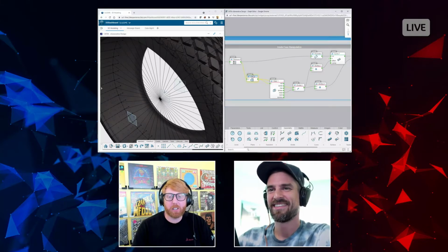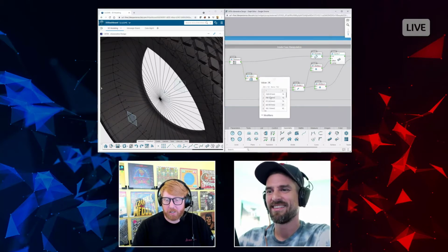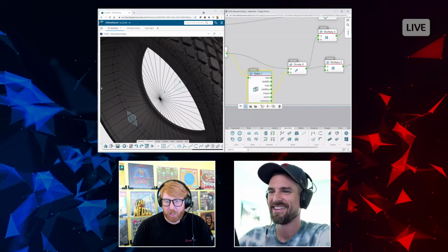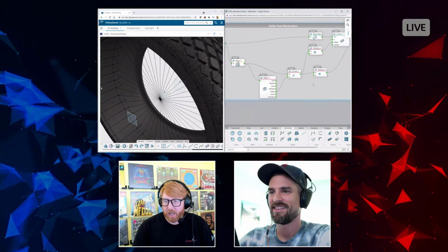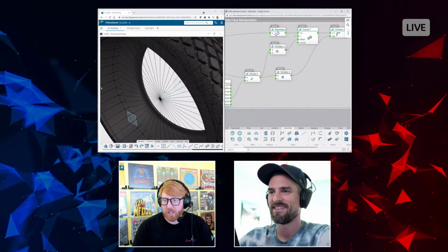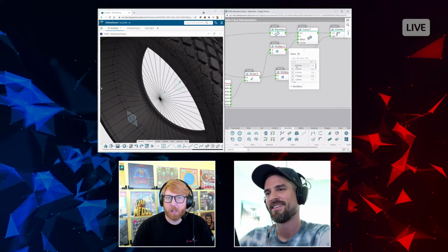So now what I do is take the surface area of all 792 nodes and run it through some logic where I get the stats and divide the surface area by the mean surface area and then multiply that by 2.5, which gives me this value right here. Now when I run it through that math, I get about 4 millimeters for this one and about 1.4 or 1.5 millimeters for this one.